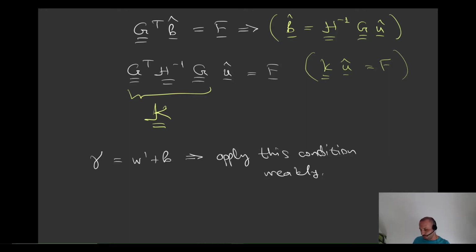And of course, I would like to also motivate you, because in the lecture notes, you're going to see another method which is called the Hu-Washizu. For that method at least, similar to the Hellinger-Reissner, the constitutive equations are also applied weakly, not only the kinematic equations that we've seen in this part of the chapter, which we applied weakly here. In the Hu-Washizu method, the constitutive equations are also applied weakly.